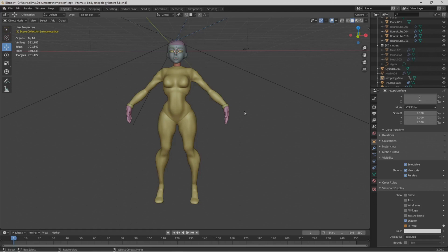Okay, currently we're in object mode. If you look to your upper left, you can see that. We also have our 3D cursor in the center of our scene. This is important because in Blender, where the 3D cursor is at, it's where objects tend to come into Blender at. If by some chance your cursor is not in the center of your scene, you can hold Shift, then press C, which will put the 3D cursor in the center of your scene.